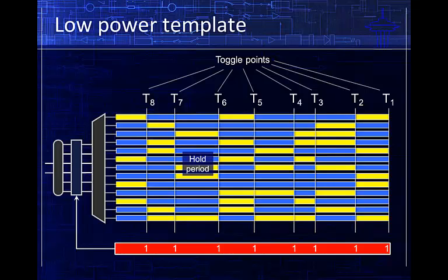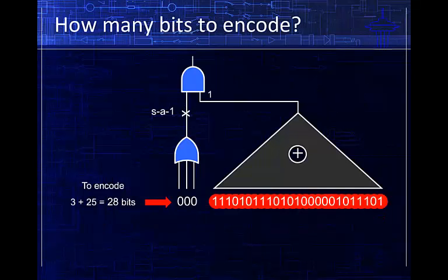The decompressor has to encode only the first value in each specified segment. If there are any other values, they have to be the same, and they're easily sustained by the hold function. The content of the template register is typically amortized across 64 patterns, so it introduces only minimal overhead.